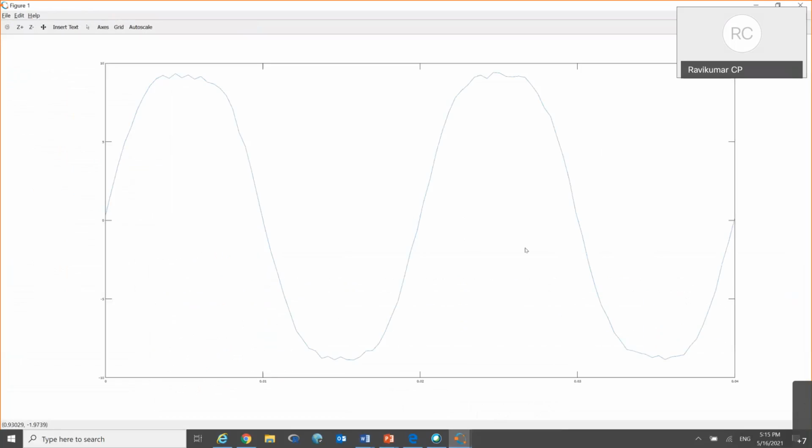So I have a bad sinusoidal. It has a 50 hertz component, which is the main component, plus there is a harmonic, which is a third harmonic, plus there is some noise also. Maybe I'm interested in knowing, if I get this kind of a noisy sinusoidal signal, which harmonics are present, right? For that, you'll have to take the fast Fourier transform of this function.